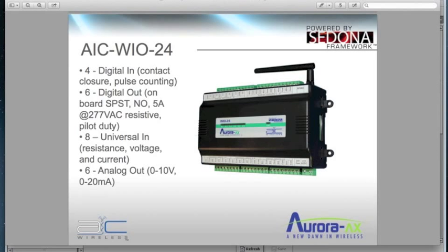That is just to keep any program logic that is based off of clocks live in the case of communication loss where it cannot synchronize the timing, or in the case of a loss of power to the device, the real-time clock will maintain its setting until power is restored to the controller. But because obviously the logic resides in the devices, constant communication with the front end is not mandated.